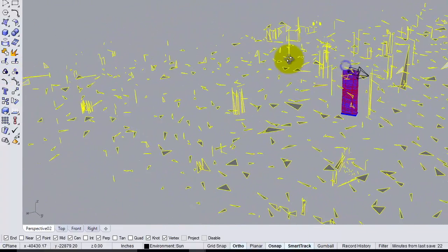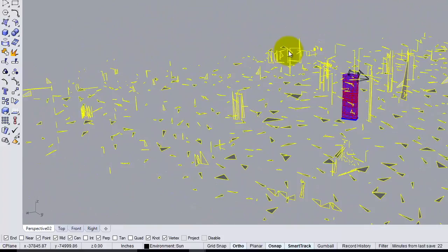So I like to present it as an option. There are a few times where this is really, really useful. If, for example, you're putting in a bunch of grass in a field and you want that grass to just appear over and over again, instead of making a really heavy Rhino file, you can use a proxy object and copy and paste the proxy object. But I at least like to introduce it as a concept so that you can see that it's there.